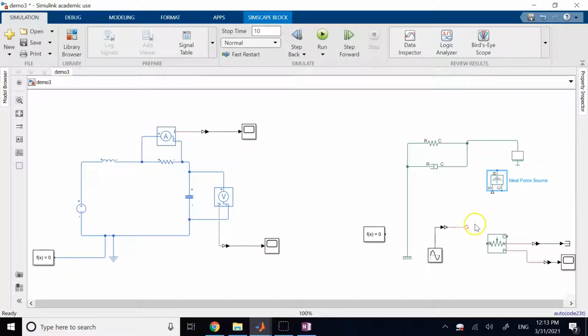Okay, so this guy will take the signal sine of t or whatever it is into its source port, and the output of that can now be connected to this block. Okay, so in order to go from the sine function to the mass, you need two intermediate blocks, one that converts your Simulink signal to physical signal, and then you pass it to a block called ideal force source, which has an input, it has an output, and then it has a reference C, and C here is the ground. It is measured with respect to the ground. So now this is my physical system.